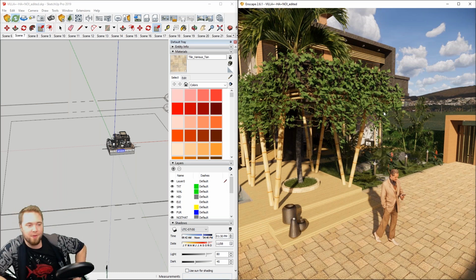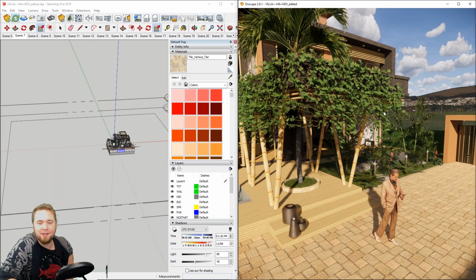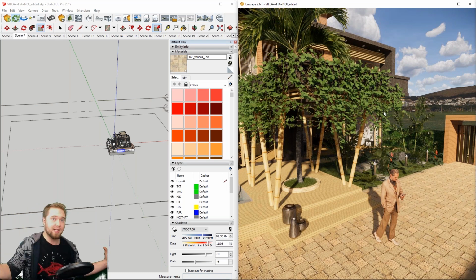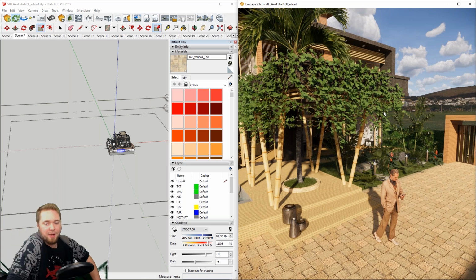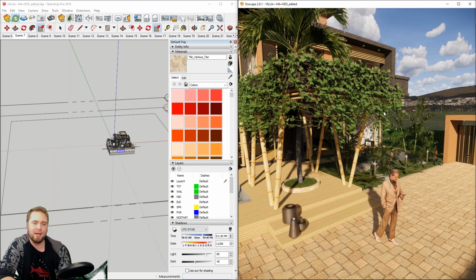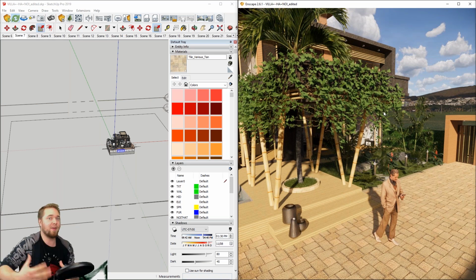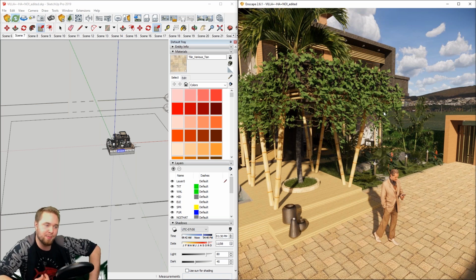If your graphics card crashes, it's rather because of a very long length of the video, or because you've selected a very high resolution. When you're exporting a video, it's likely that your graphics card RAM is full. Your graphics card RAM is where things are being stored that are being presented at that time in real-time 3D. So your graphics card might crash because you have tons of very high quality textures in your project. Those all lie around on that graphics card and they take up the most space.